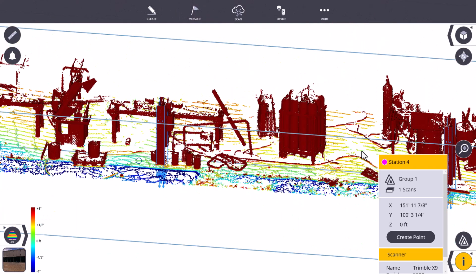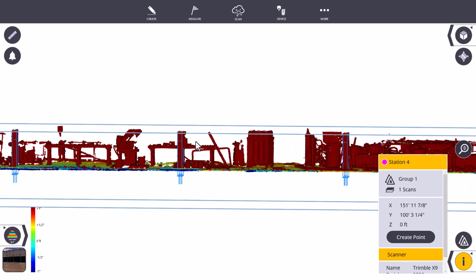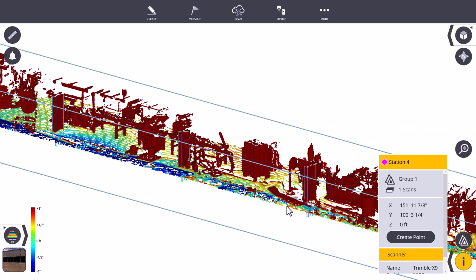Obviously, in an existing structure, you're going to see it move quite a bit. And even right here, you can see it's higher, probably sloped down so that if water got in, it would drain away. Reference elevation is probably better off as either a pin in the ground or a mark on the wall, a 4-foot mark, 5-foot mark, so that I know what I'm pulling to. But that actually already looks good.